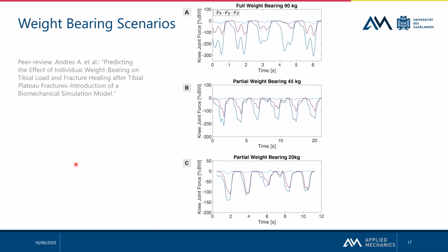We implement the text files containing the timestamps from the ground reaction force and the novel load pads, and we use an input file and an interpolation function to apply all these ground reaction forces to the foot segment, and have all this data in AnyBody to then calculate the specific knee joint forces. But it's also described in every detail in the paper, so you can read what I do.